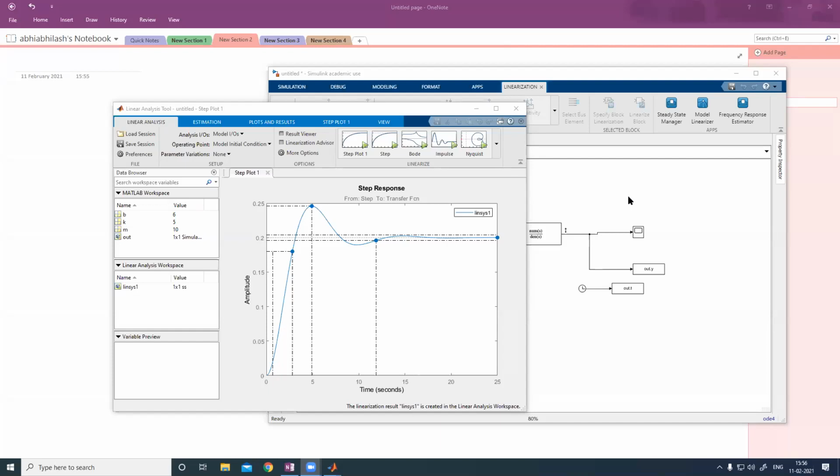Sir, the transfer function of the system. Yeah, 20 log of the transfer function. Why are you using 20 log? Because we are giving a signal and it's not a power. If it's a power signal, then we would have used 10. Here it's a normal voltage or current signal. Why are you using log?